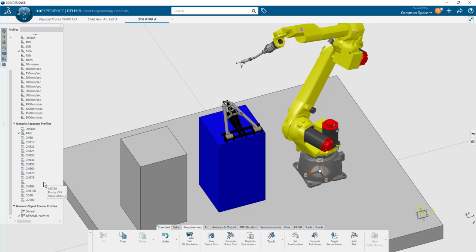And the way to do that would be to upload the program from the manufacturing robot before you start programming it. Now you can upload the program and it only has to be one location from the robot on the manufacturing floor. But what you would do is you would take a robot controller dump and you would bring that into the simulation environment.